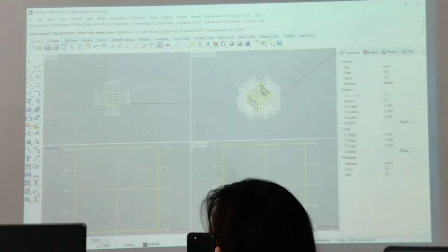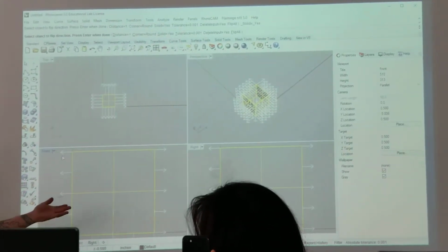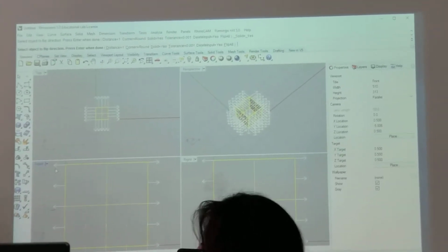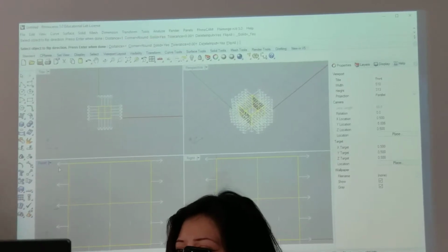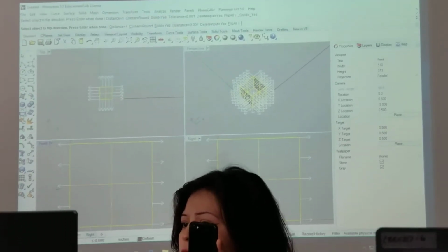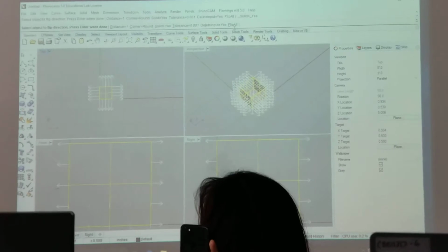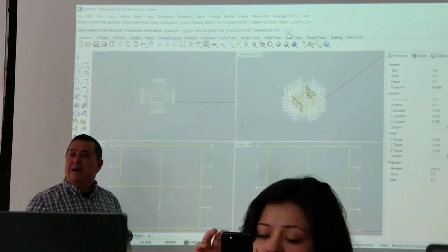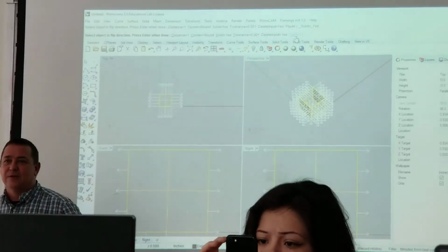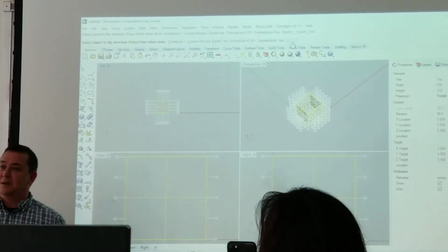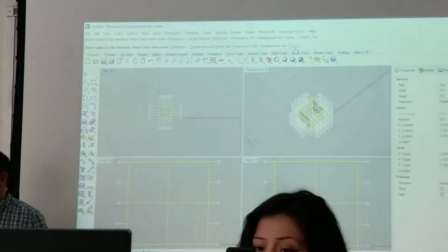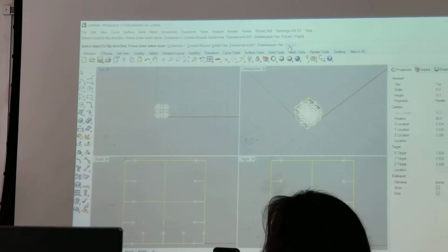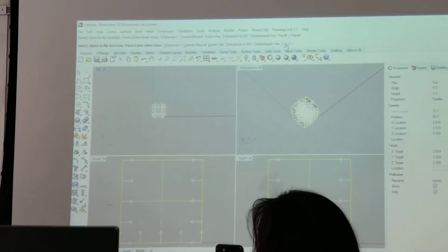Alright, it's only showing it to us now because it wants to know which direction we want to add thickness. And I want to add it inward. I want my cube, when I'm done, to be 1 inch by 1 inch. So I'm going to choose up in the command prompt here. See, the command prompt's got a bunch of options sitting in it now. Rather than open a separate dialog window for everything, it just puts options in the command prompt. Choose flip all up there, and all your arrows will turn around the other way. Great. So that option just executes when you pick it.